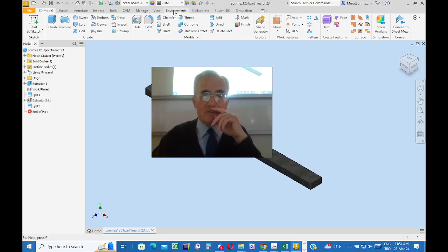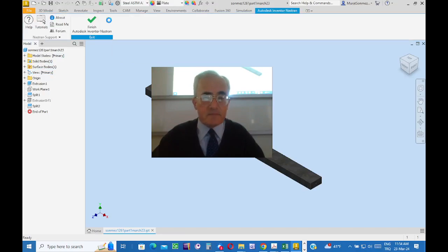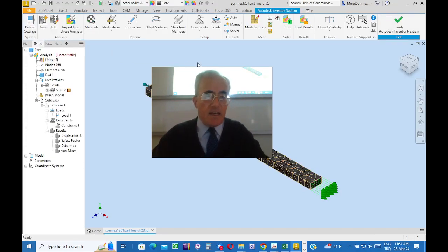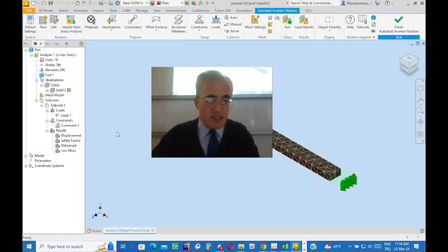Okay, click on the environment tab, and then select the correct option for studying the same problem: Nastran, of course. We have already used Nastran in the first session.